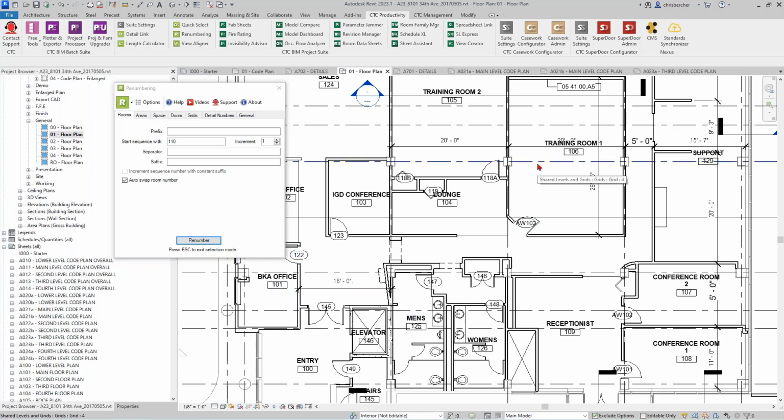And maybe in healthcare you do buckets of 10 rooms, right? You have blocks on a floor, so maybe not all numbers get used, or in suites and office buildings. Whenever you get to the end of your sequence, change the starting point to be 120 or 130. Whatever you need it to do. You can also set increments. So maybe you didn't want every single one, but you wanted every fifth one, or it's 110, 120, 130. Go ahead, set your increment to 10 and start at 100 or 200 or 1,000. There's no real limit to what you can do with this.